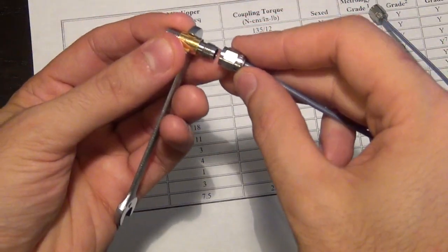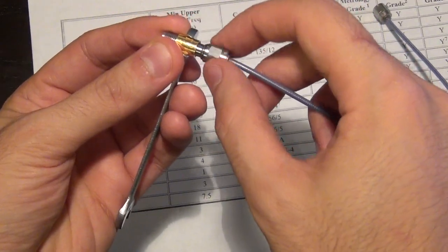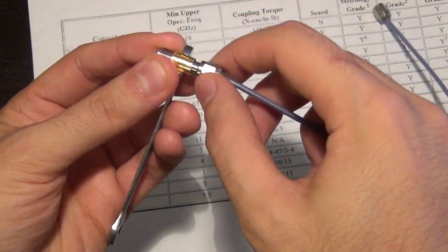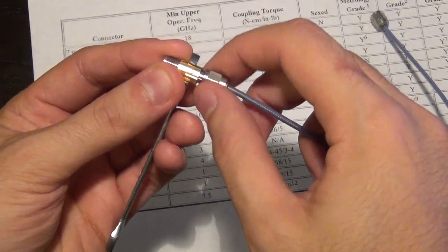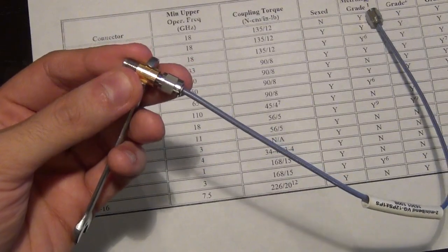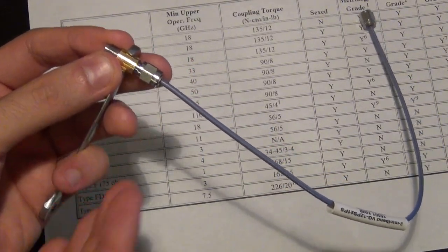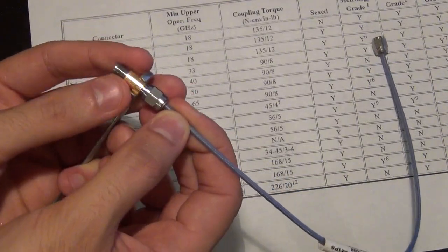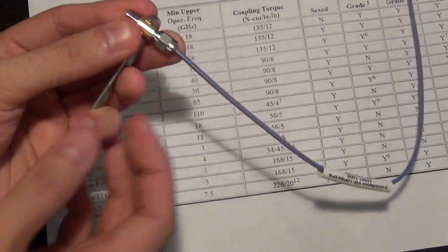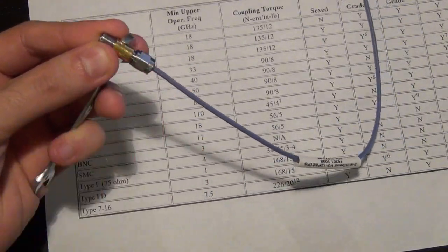Make sure that you're perfectly centered, place the connector inside, and gently turn it. If it's not turning really easily, then it's not done correctly. You never need to force any of these connectors, because all of these connectors are precision machine grade, and they will fit in perfectly within each other. If they don't, you're doing something wrong. So at this point, I'm holding this wrench in my hand, and this connector cannot turn, and I have hand tightened it as much as I could.